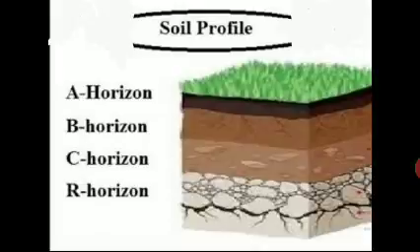The fourth one is porosity. Porosity is defined as the ratio of volume of voids to the total volume of soil mass including that of water and air. It is expressed as a percentage. Voids ratio is defined as the ratio of volume of voids to the volume of soil solids. It is expressed as a ratio.